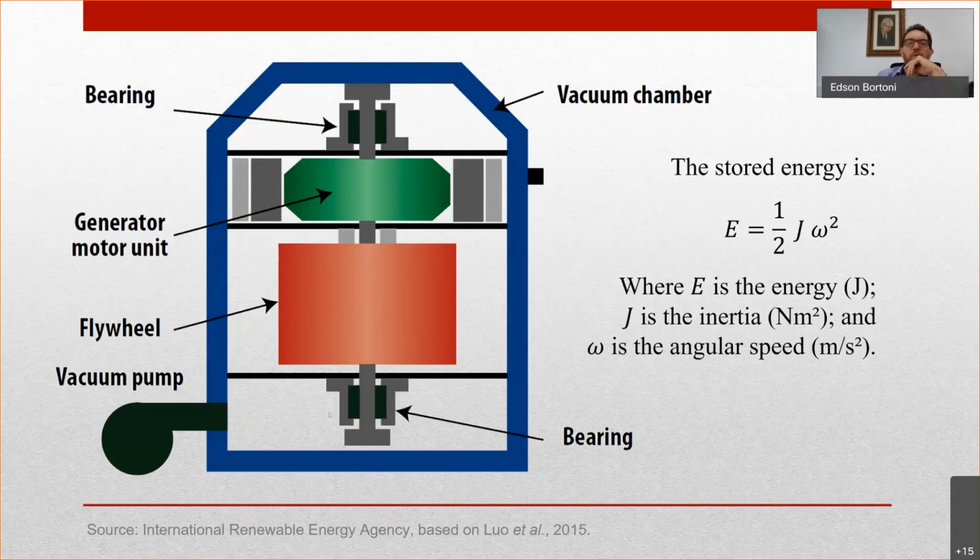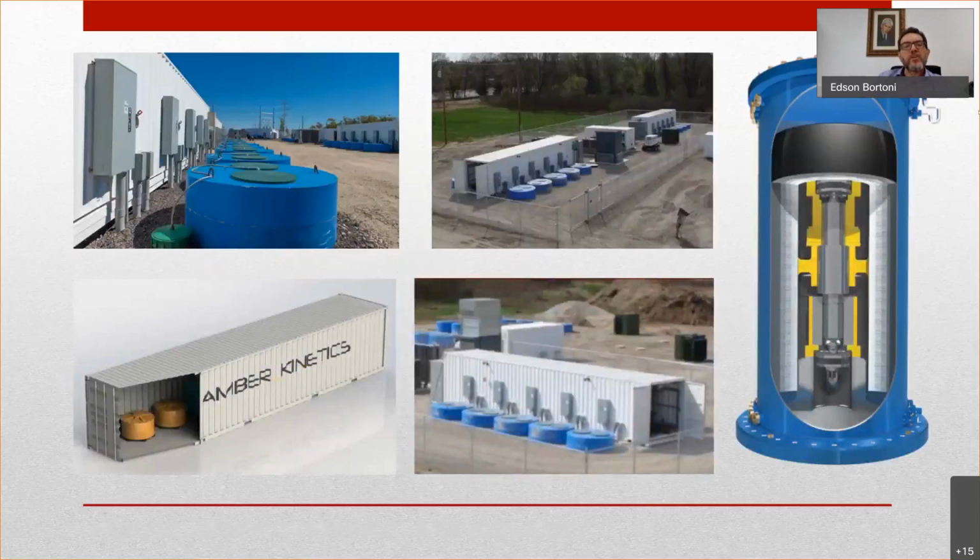Of course, we will try to reduce the wasted power in the bearings and in friction and ventilation using a vacuum chamber, so you can reduce those losses and increase the stored energy. Applications throughout the world.